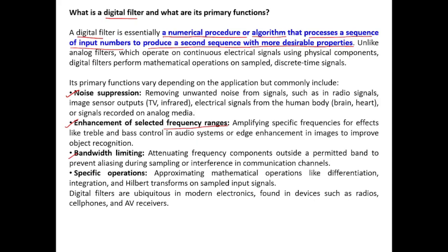the example of heart rate monitoring. We take the ECG signal, then we band limit the signal in the range of 16 hertz to 22 hertz, to extract the significant component of the QRS complex. Then we process it further. During that processing, we get some peaks.